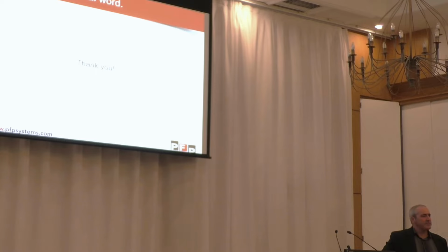Yes, sir. I noticed with the client's specifications, was I reading galvanised steel? For piping. You wouldn't put zinc under insulation. No. So that's probably why you went to F. Yeah.